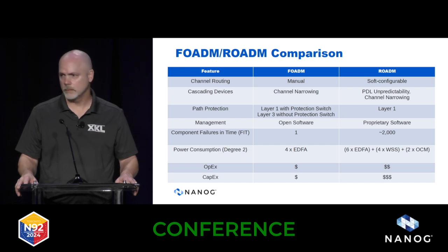Management-wise, the software is fairly trivial for a FOADM. You just have to be able to manage the amplifiers, basically. And so that can be done with whatever your existing management tools are. But with a ROADM, it's going to be using the proprietary software.